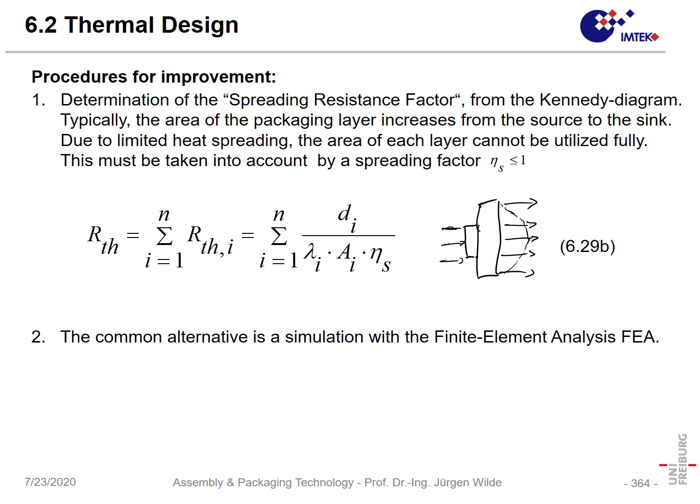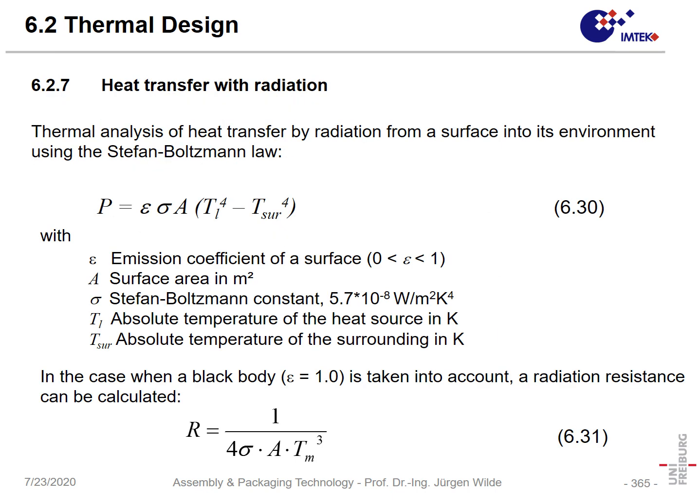And to that purpose, so-called spreading factors can be introduced, but I will not go into the details. If you are interested, you can look for the Kennedy diagram, and then it can be estimated. In our exam, we just take an estimate of how the area would be, and we assume that we have ideal spreading of the heat, which is not really the true case, but it's the first estimate.